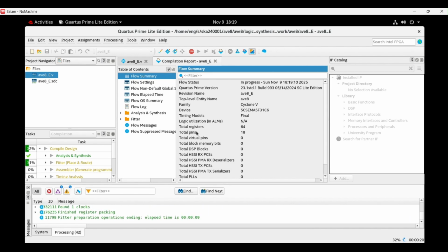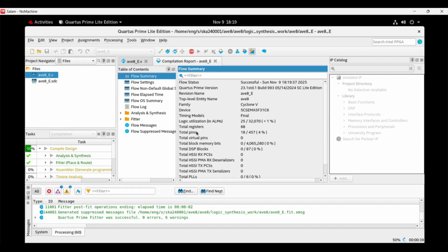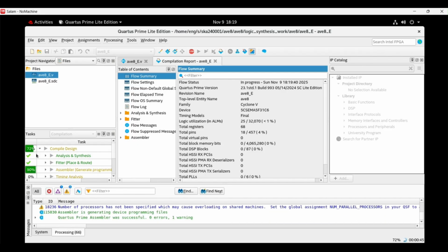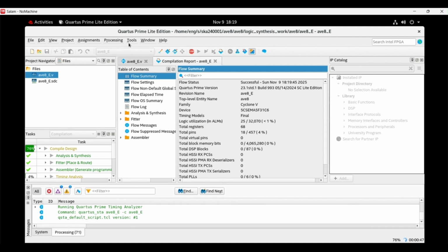Our next step will be verifying the design by testing both codes, the C++ and the Verilog code, providing them with the required input to see how they perform and whether they give the exact same result for the design or not. So that will be our next part. All right, to do so right now, I think it's going to work. That's fine. And after it finishes, I'm going to show you the RTL design and all these things.